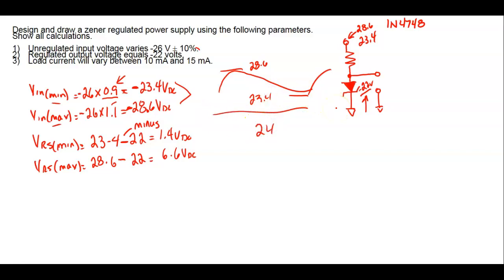Well, what we're doing is we're regulating down here. So that means I'm cutting off the garbage that's changing, right? You understand? And I get a good regulated voltage. So this is why you always have to regulate below what your regulated variation is going to be at. You have to regulate below that. Because if we try to put our regulator up in here, then the output is going to see these dips and stuff in there. Any more questions?